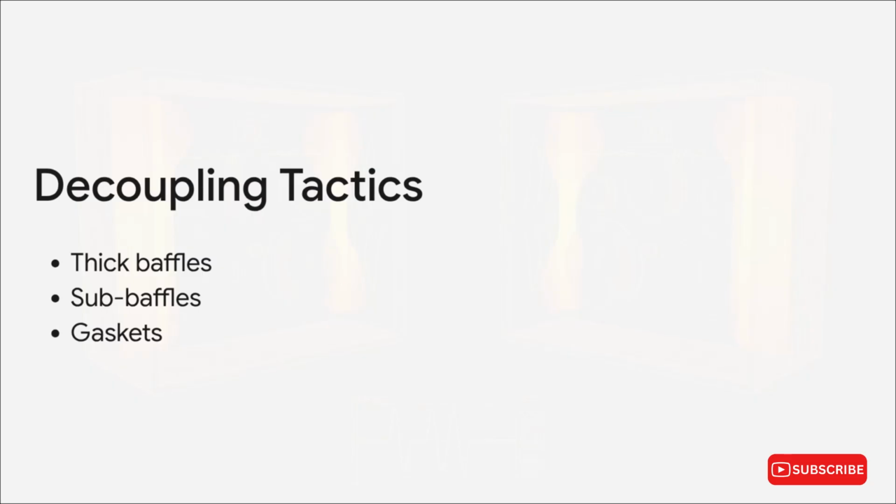To counteract this violent mechanical energy, structural engineers employ some very strict decoupling tactics. This includes things like drastically increasing the baffle thickness or utilizing complex dual material construction, like physically mounting rigid aluminum plates directly onto an MDF board. It also involves mounting the drivers themselves onto isolated sub-baffles and using heavy damping gaskets to prevent direct energy transfer from the driver's frame straight into the cabinet skeleton. The ultimate goal here is to either purposefully add calculated musical life to a guitar signal or to ensure absolute clinical precision in a studio monitor without any blurring whatsoever.